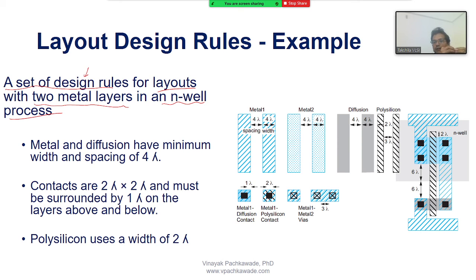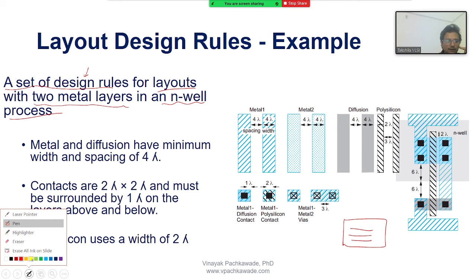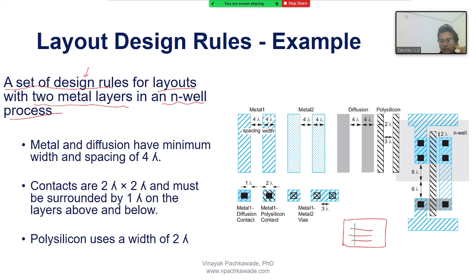to connect the transistors together, let's say 10,000 transistors, and then we'll make a chip, right? But the advantage of having more metal layers is obviously you have choice and flexibility during place and route of your chip, because you have extra metal. So when you have a chip area like this, you can use metal one for all horizontal lines, and then metal 2 you can overlap on top of that, so they are not shorted.